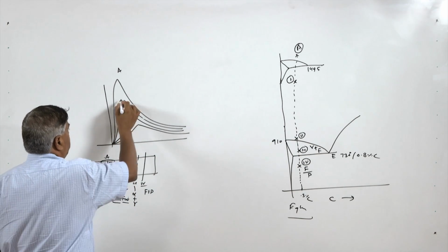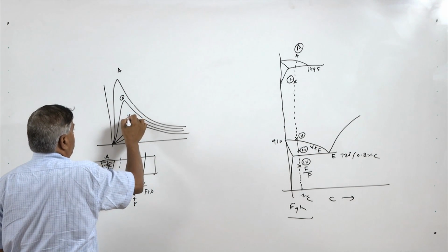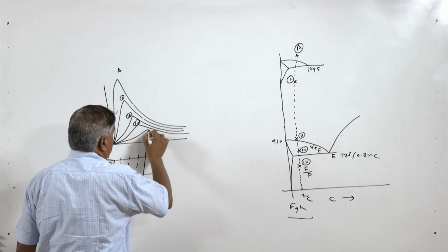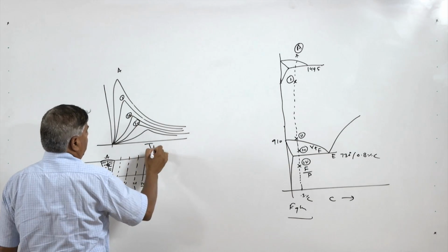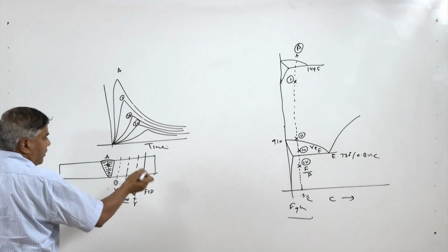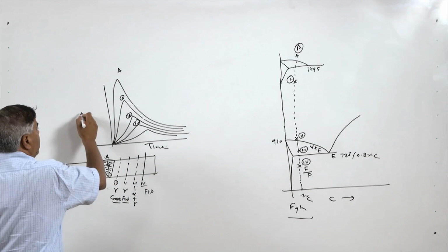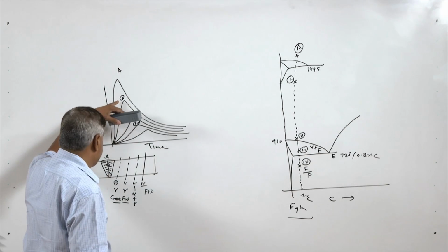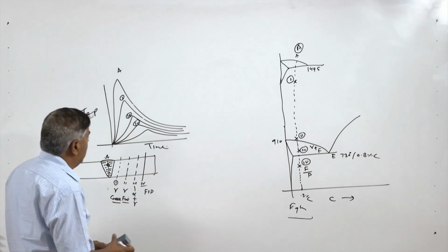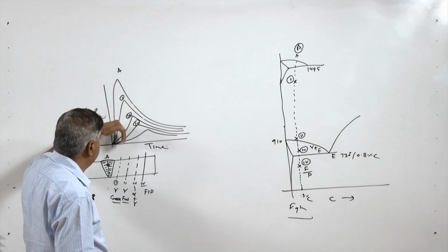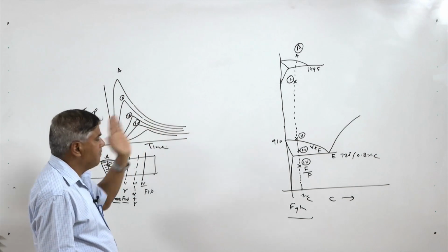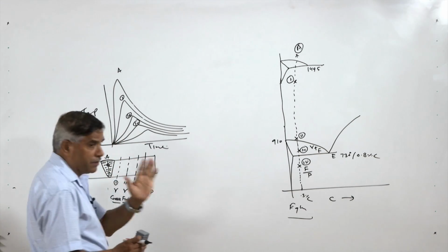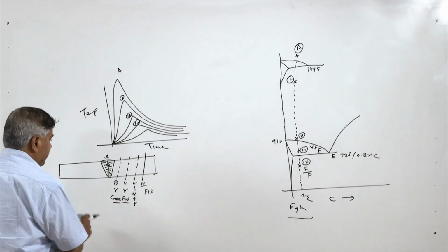If we see the weld thermal cycle for 3 or 4 different zones, we will see that point 1 experiences a much higher temperature as compared to points 3 and 4, but it takes a shorter period to reach there, and a longer time to reach the lower temperatures at the points located further away from the fusion boundary.